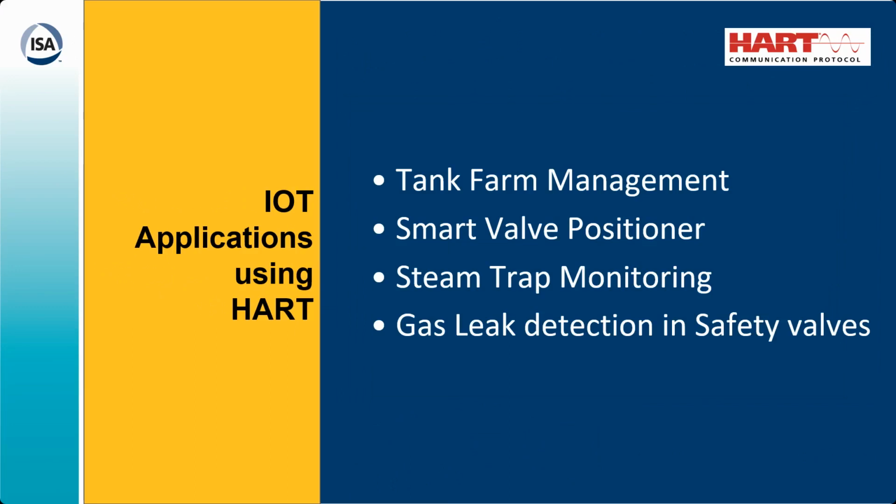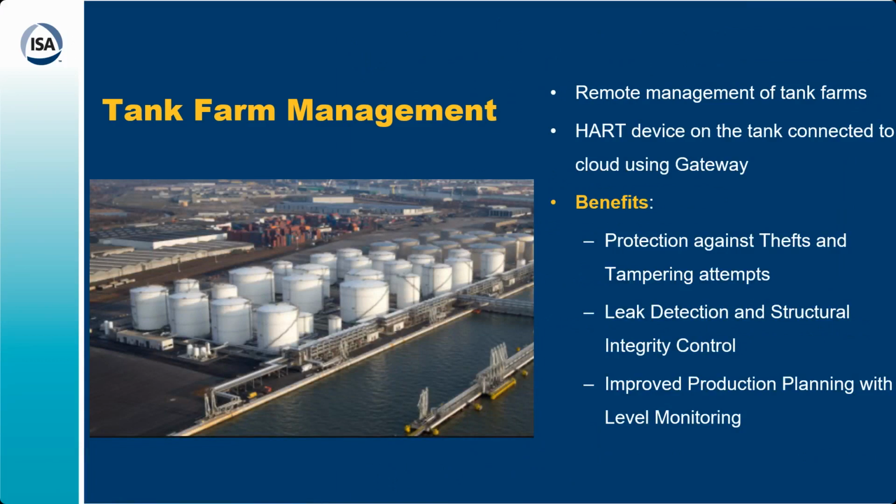So let's talk about some of the IoT applications using HART. We will talk about tank farm management, valve positioners, steam trap monitoring, gas leak detection, and all. When you have tank farm management, there are many tank farms situated remotely. So you have to do remote management of your tank farm so that you can protect your tank farms from thieves or tampering attempts. There are leak detection systems available. You can do structural integrity control.